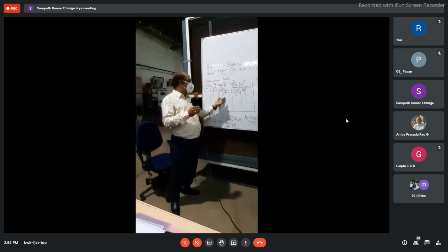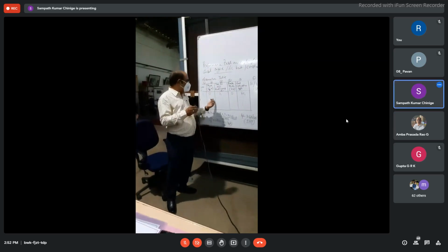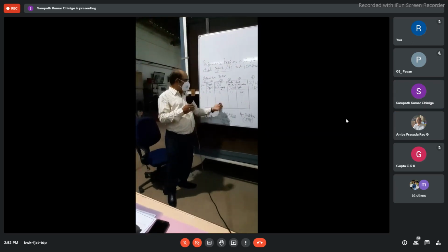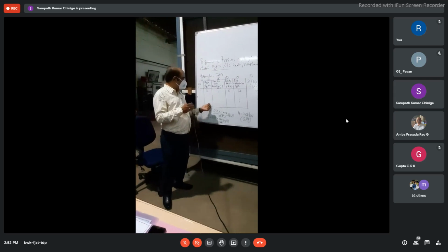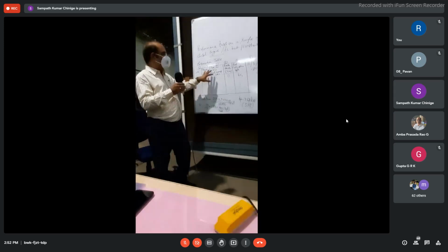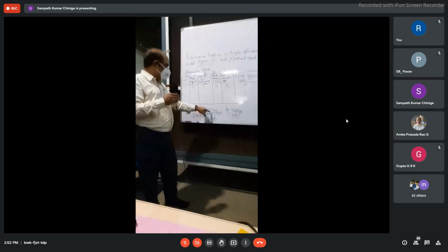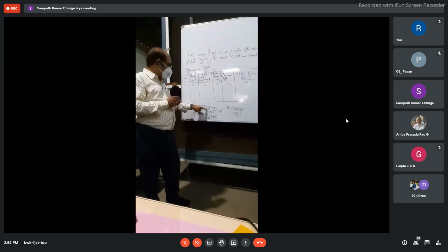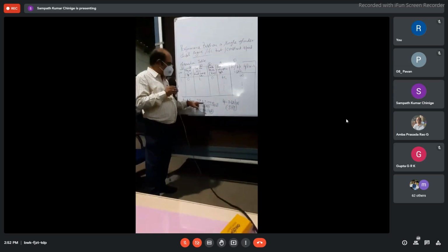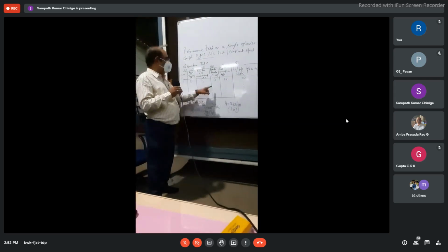So T1, then T2 corresponding to 0.5 torque meter reading, T2 for 1, then T3 for 1.5, T4 for 2.5, let us say. So note down these values. Now you come to the calculations. The next step: because the only variable here is torque, as we maintain the speed constant, in this formula the only variable is torque. So for the first reading, when you put T equal to 0, the whole value is 0. So brake power is 0.